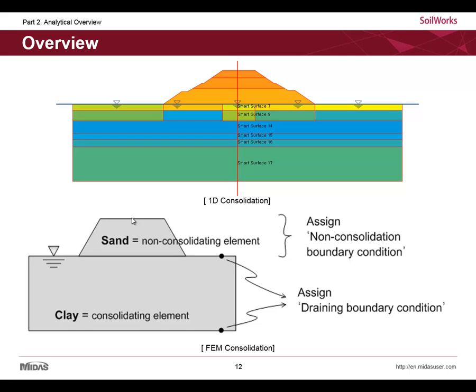During this process, the soil particles will get closer to each other and accumulate over time, meaning that the soil will experience settlement in the direction of gravity. So consolidation analysis is largely classified into the theoretical one-dimensional consolidation analysis method and the finite element method.